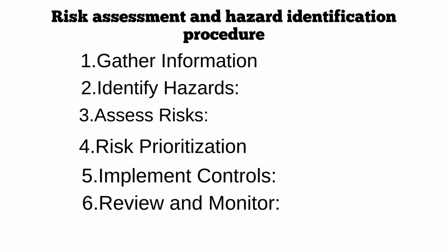Developing and implementing control measures include engineering controls such as physical barriers, guardrails, or safety net to prevent the falls. Ensuring that structural integrity of scaffolds are intact and even platforms are stable. While implementing control measures, we must consider administrative controls, means establishing safe work procedures, providing adequate training and supervision, enforcing use of personal protective equipment.